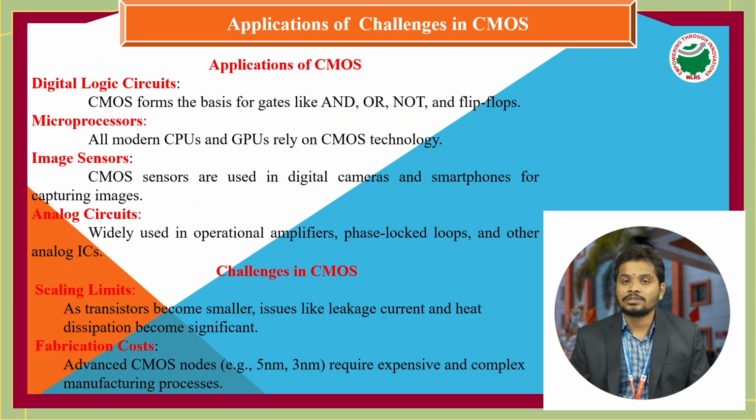And what are the challenges in CMOS technology? The challenges are scaling limits and fabrication cost. As transistors become smaller, issues like leakage current and heat dissipation become more significant. Those are called second order effects. As the channel decreases, the source-drain length decreases, which makes it easier for electrons to jump from drain to source, but this leads to more leakage current because the distance between the gate and channel also decreases. So this is the main challenge for CMOS technology.